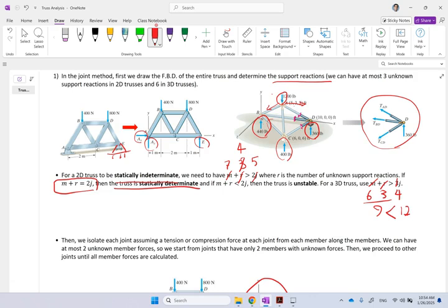There is no support for x or z motion, so this truss is going to start moving. The way it is shown, it is really unstable. Right now, because the force is in y and all reactions are in y, everything is good. But if you add more forces in x or z direction on any of the joints, the truss starts to move, and that will not be static anymore. That will be unstable. Okay? So you see how we can have different scenarios here.